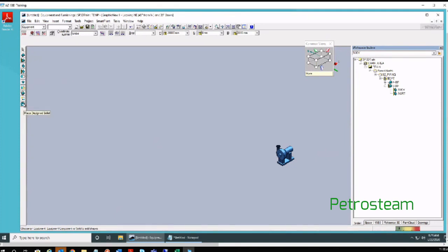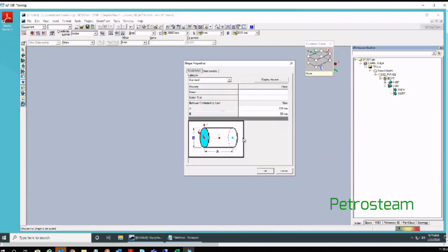Solid means, I will show you this solid option later. This is what solid is. So you can select either of these. For me, as I am building the body part, I will select this equipment component so that the shapes which I am placing will not come directly under this, they will come under this component.